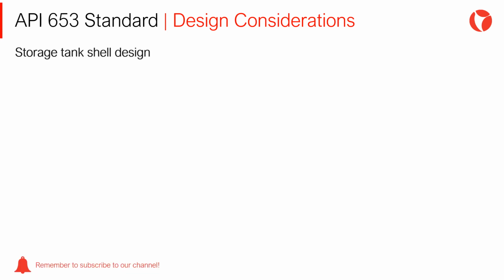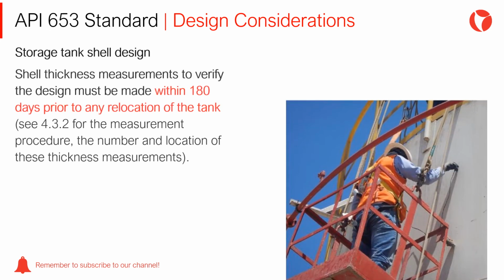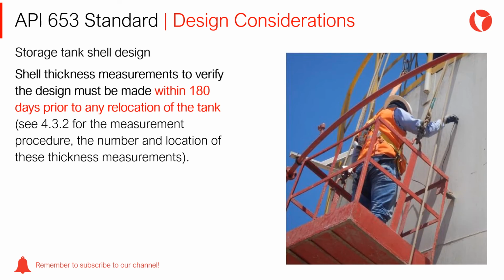For example, storage tank shell design. Shell thickness measurements to verify the design must be made within 180 days prior to the relocation of any tank.